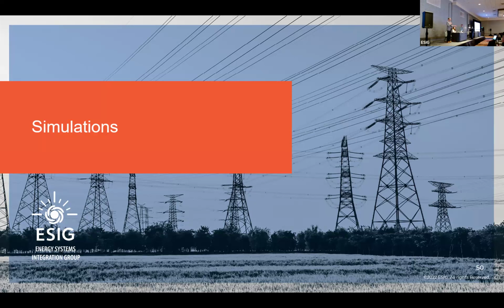So on the DC link side, I think it's first important to acknowledge that not every IBR has a similar looking DC link. It depends on what the technology is. On the simpler side, a battery system has a DC link that looks one way. On the PV side, the DC link is more power electronics, if you will, but just silicon panels.